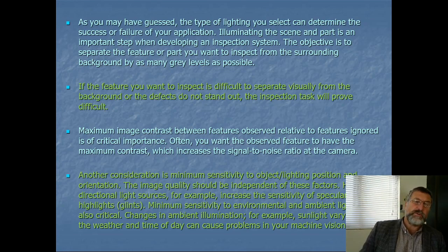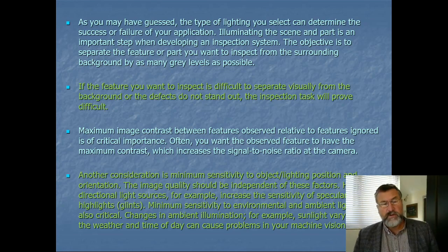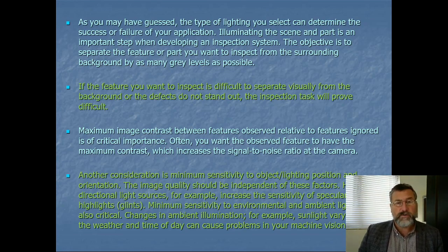That's very useful because we can shine it at, say, an object, and we can scan it over the object or put the object on a conveyor belt. This is a standard technique in 3D machine vision to recover data from 3D objects by scanning them with a laser. We call it laser triangulation. It's quite accurate. It has a disadvantage that the laser is typically a bit expensive, but it is accurate, and it's used quite commonly in industry.